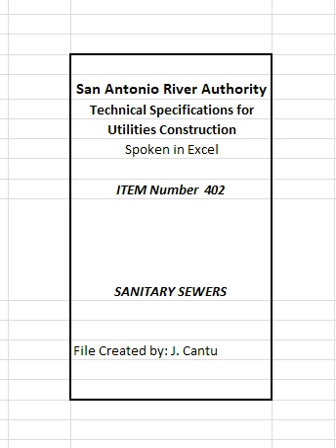3. Concrete pipe. Concrete pipe will not be permitted for use as sanitary sewer transmission line. 4. Asbestos cement pipe. Asbestos cement pipe will not be permitted for use as sanitary sewer transmission line. 5. Polyvinyl chloride, PVC, sewer pipe.